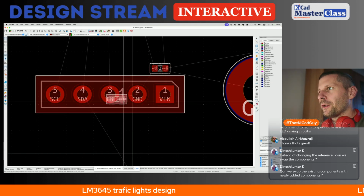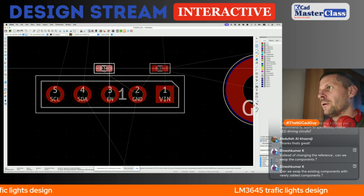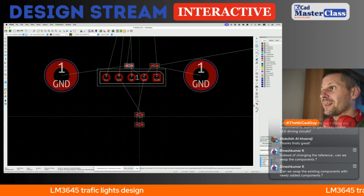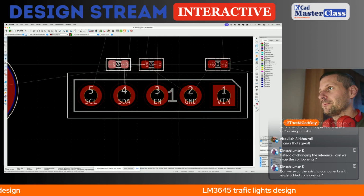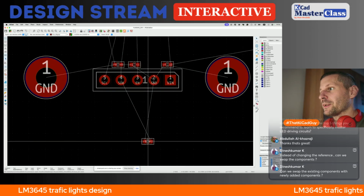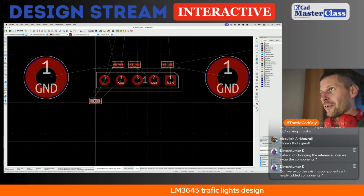This will be our ESD diodes. I highly recommend to place them in the same direction, despite the fact that these diodes are symmetrical, bidirectional. Doesn't matter, because the pick and place machine likes to place the components with the same rotation to avoid twisting around.